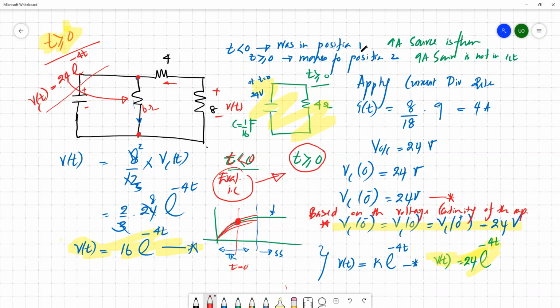So then you have to keep the capacitors and inductors as they are, apply Kirchhoff voltage law, get the differential equation, solve it and find the voltage or current response. Then substitute the respective values for t to get the exact value at this point.